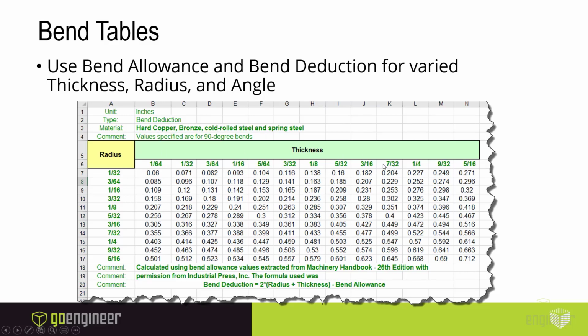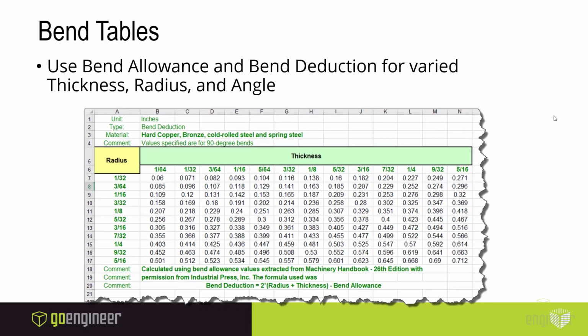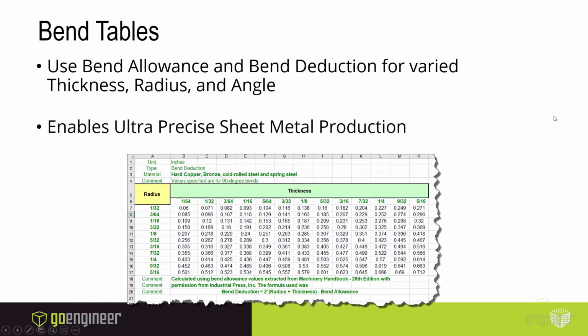And when you're talking about forming equipment or press brakes, you're talking about very tight wedges versus very loose and round, and that's again a difference in tension and compression. But these are where companies up things when they want to get that ultra precise thing. You're not just using one number of a K-factor, you're using an individual unique number for every nuance within the part. And those again get incredibly granular.